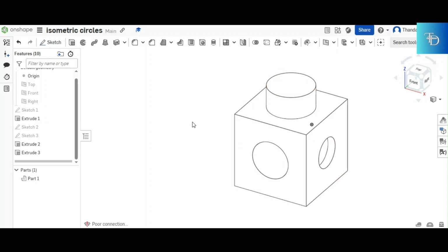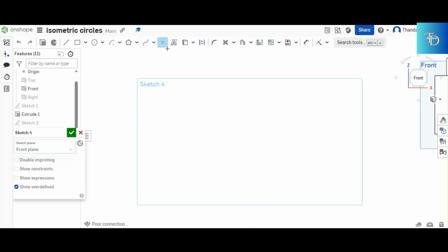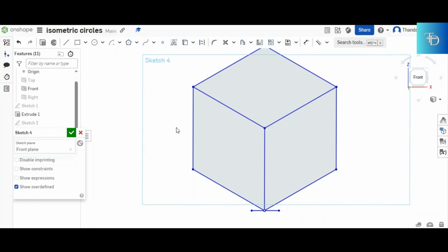So now we're gonna go over and draw all these 3 faces so that you're gonna be equipped with all the skills. Each side of the cube is 100 millimeters, which means that side right there is 100, 100, 100, another 100, resulting in a square. Alright, we all know that when you're about to create an isometric, you draw an isometric box first. So already our drawing has a cube whereby each of the sides is given as 100 millimeters. So now let's start by drawing the circle that is at this face first, and then we're gonna continue to go over and deal with the other surfaces.